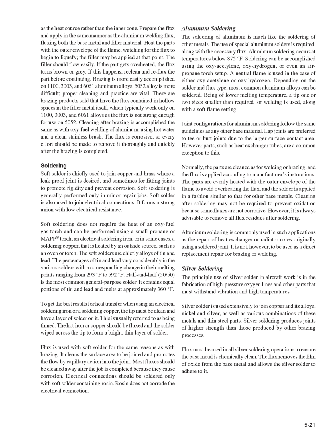It cleans the surface area to be joined and promotes the flow by capillary action into the joint. Most fluxes should be cleaned away after the job is completed because they cause corrosion. Electrical connections should be soldered only with soft solder containing rosin. Rosin does not corrode the electrical connection.